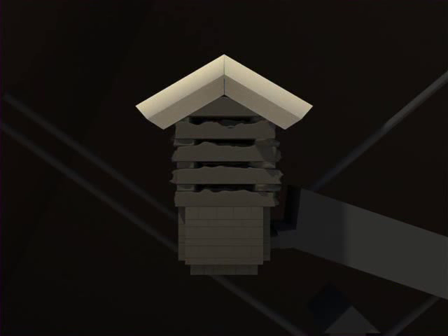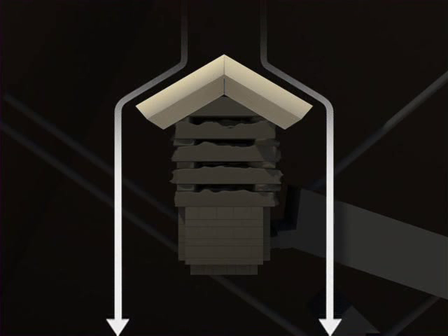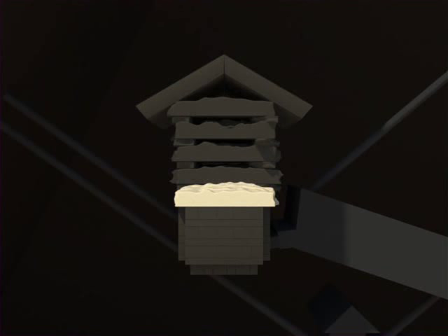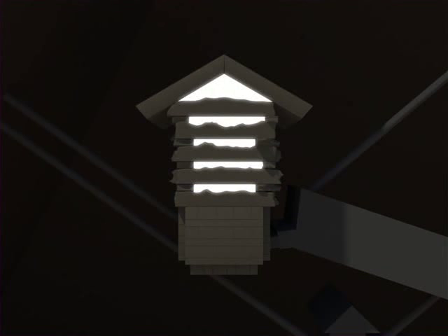That pointed roof on the uppermost chamber deflects the load laterally around it, as all arches do, so that the king's chamber roof slab carries only its own weight. The remaining 4 chambers are probably just there for structural redundancy. If the upper one collapsed, then the lower ones would continue to provide that same structural function. It's really an ingenious arrangement that evidently has done its job well. We'll see this technique again during the Roman and medieval eras in a device called the relieving arch.